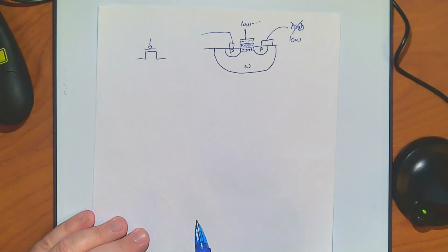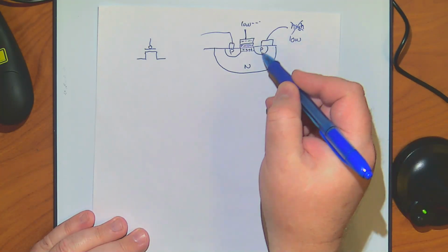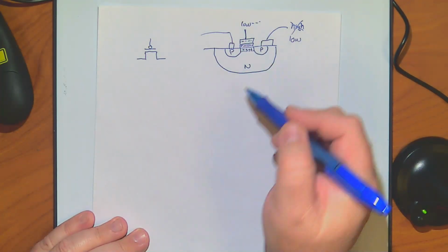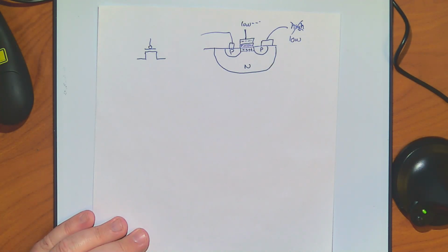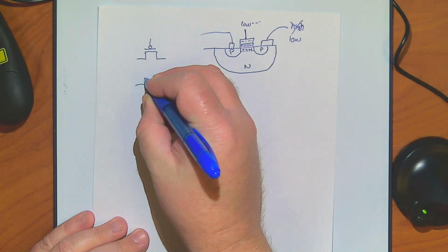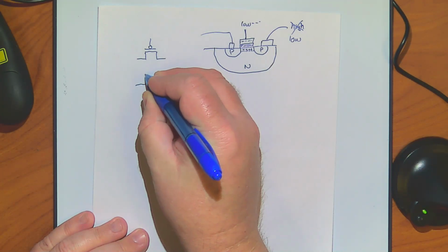So can this pass low? No, it can't pass super low, because for this side to go over to this side, I have to have that channel, so this has to be lower. It won't work. So my PMOS will not do a good job on passing. Does that make sense? Okay. This becomes really important for transmission gates, so that's why I'm just reviewing it.